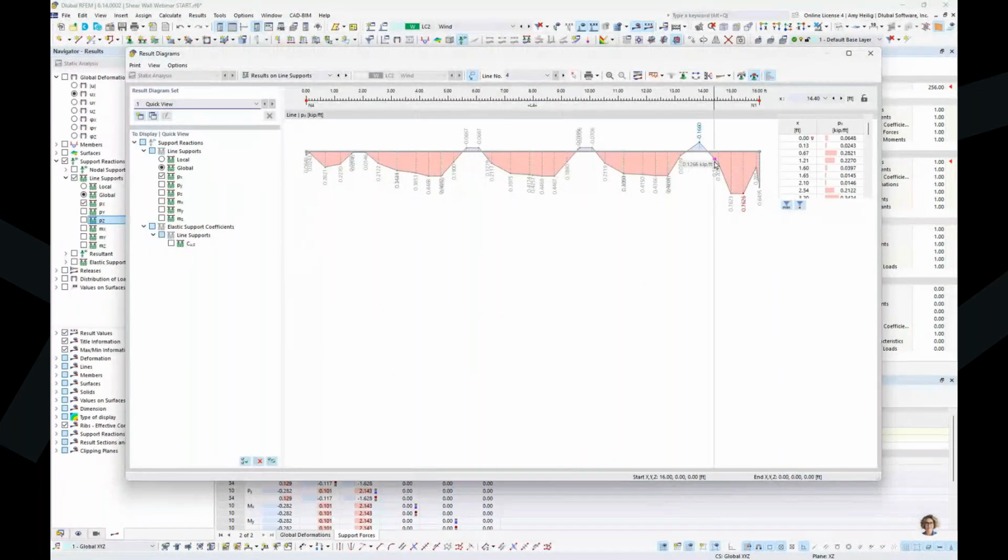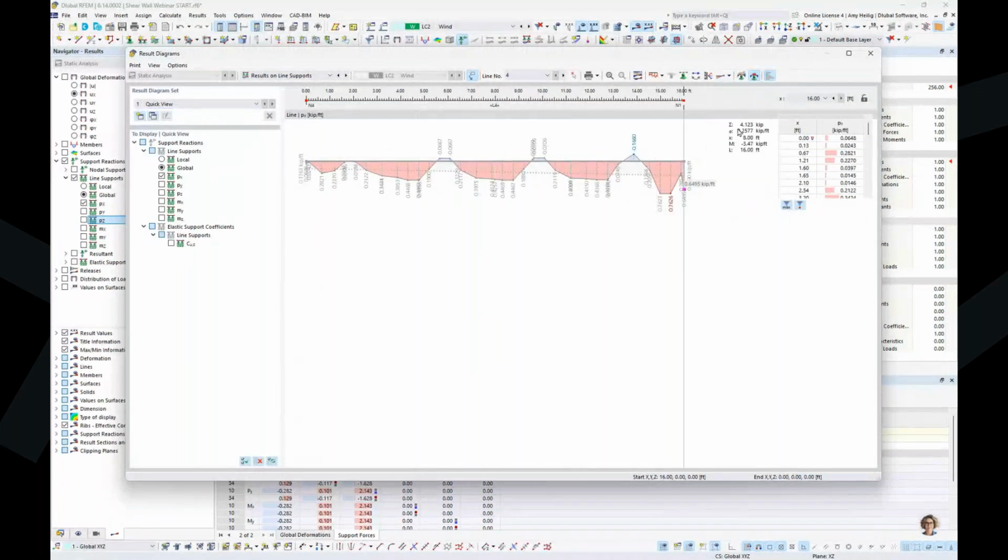along the length. We have the ability here to display the linear smoothing, which is going to give me the total shear force, or the total shear force as a unit of length. This is what would be used to design those anchor bolts or those shear connectors.